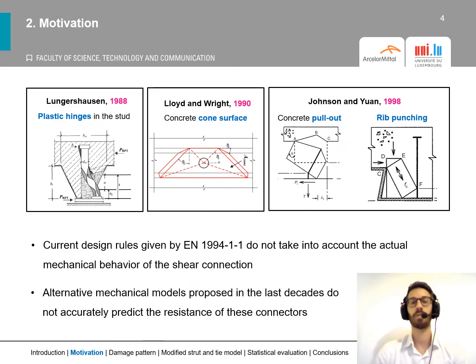However, current design rules for predicting the strength of studs given by Eurocode 4 do not take into account the actual mechanical behavior of the connection. There are some alternative mechanical models proposed in the last decades, but they do not accurately predict the resistance of these connectors.